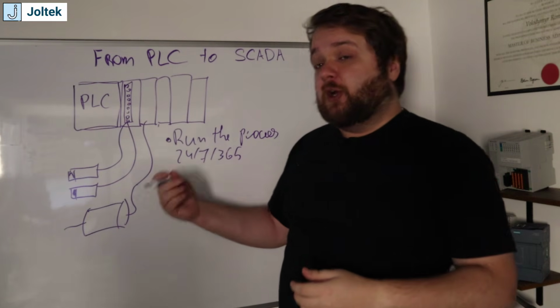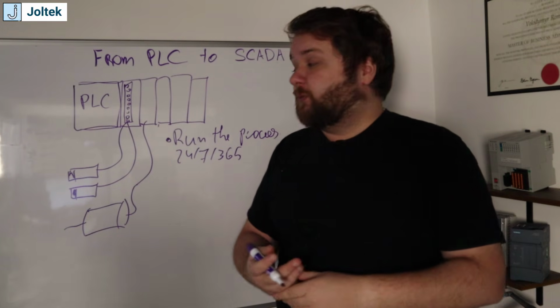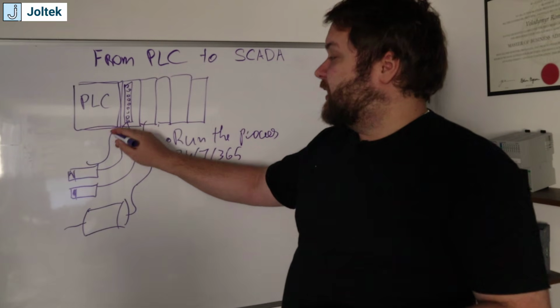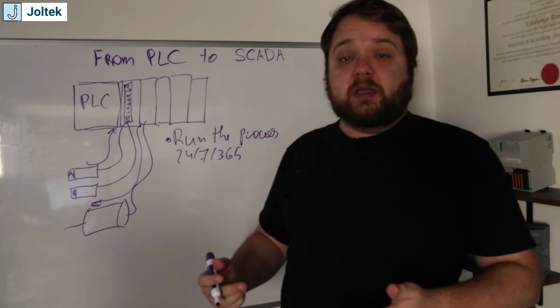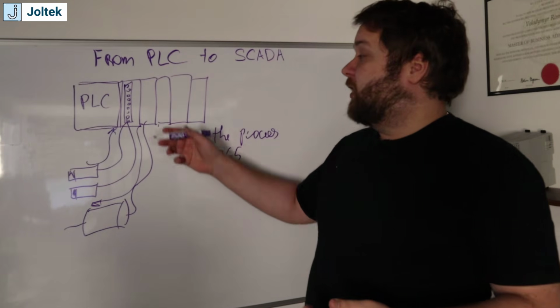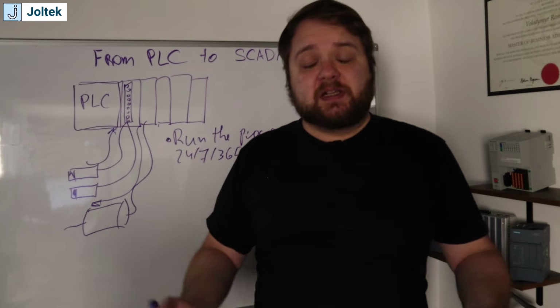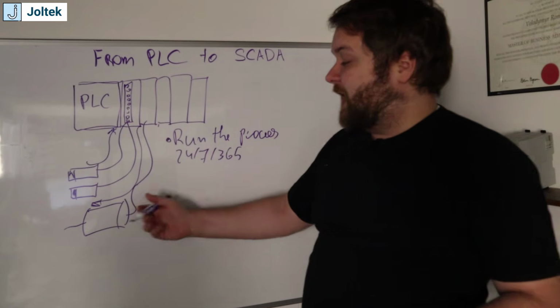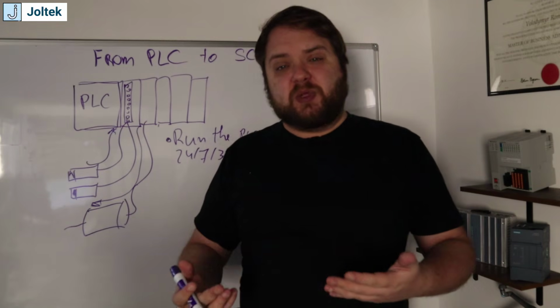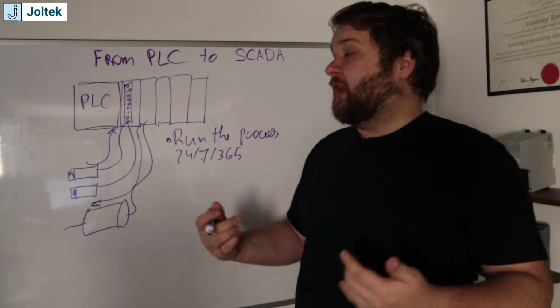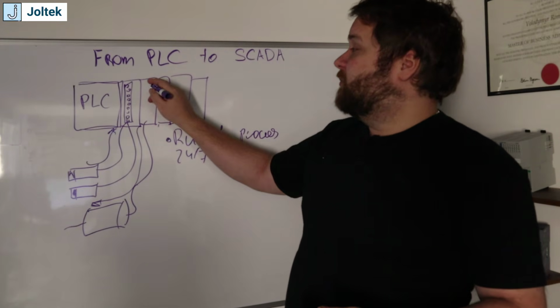So for example, your PLCs are going to be extremely fast. From your input side going into the PLC and then actuating the motor, it could be milliseconds, right? Depending on how long it takes to run the logic, sometimes it's milliseconds and it's going to activate your output. Similarly, there's going to be high-speed input and output cards that will react very quickly. You also have safety modules, right?